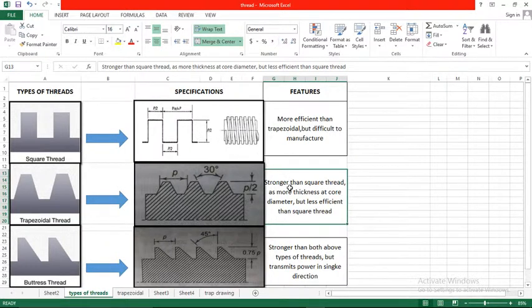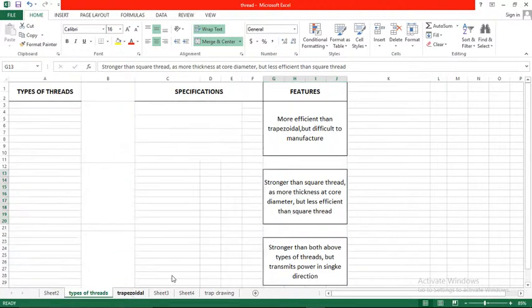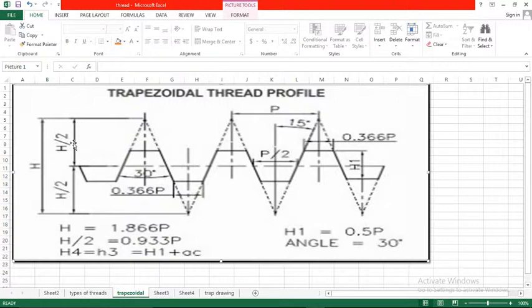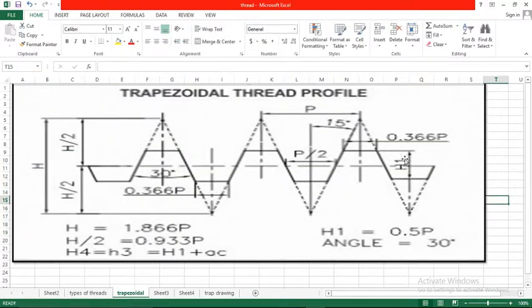When I tried to look for a drawing sheet for the complete bolt, I did not find any drawing which gives every detail about these trapezoidal threaded bolts, but this is what I found here. I think the tooth profile is the most important thing, so I am going to design this, and the dimensions will be taken from this image here. The most important things about the profile are this 30-degree angle, this height, and this width.